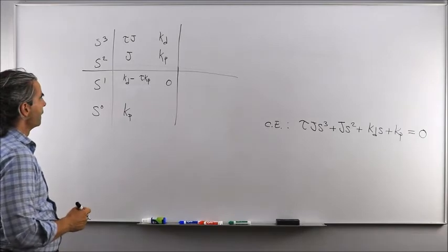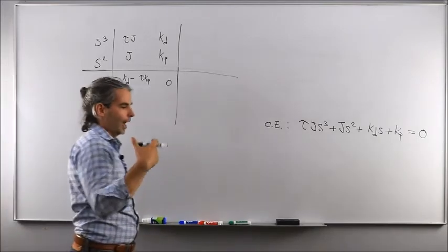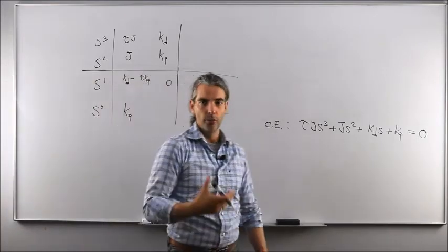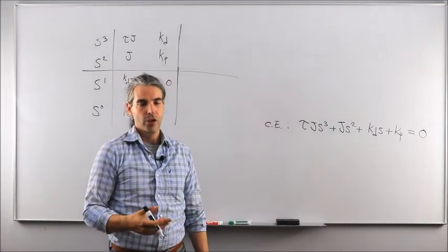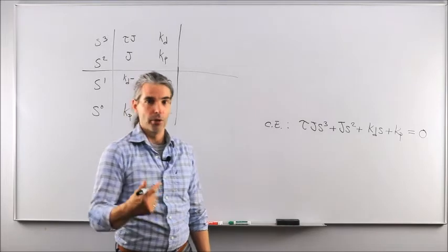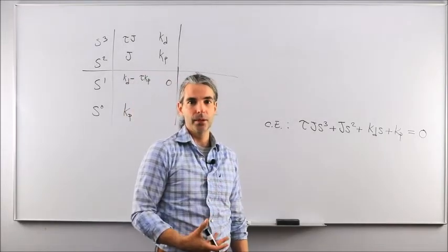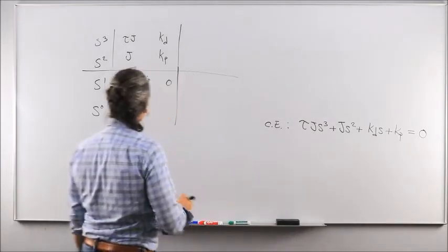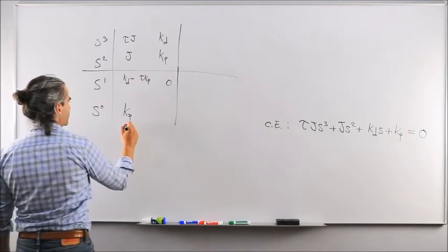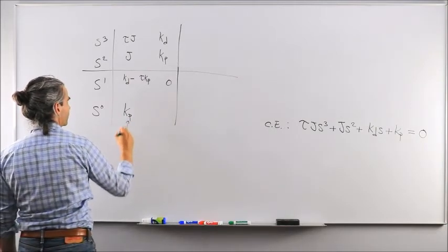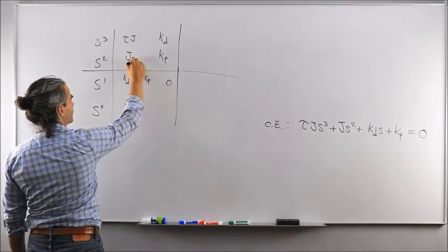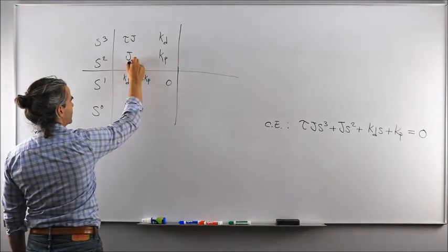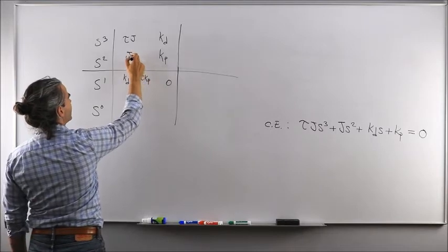Nice. If you happen to have designed your modified PD controller correctly, you will always end up with Kp and Kd being positive values. Okay? So this is going to be a positive value here. The J is the inertia matrix along that axis of interest, the principal moment of inertia, positive.